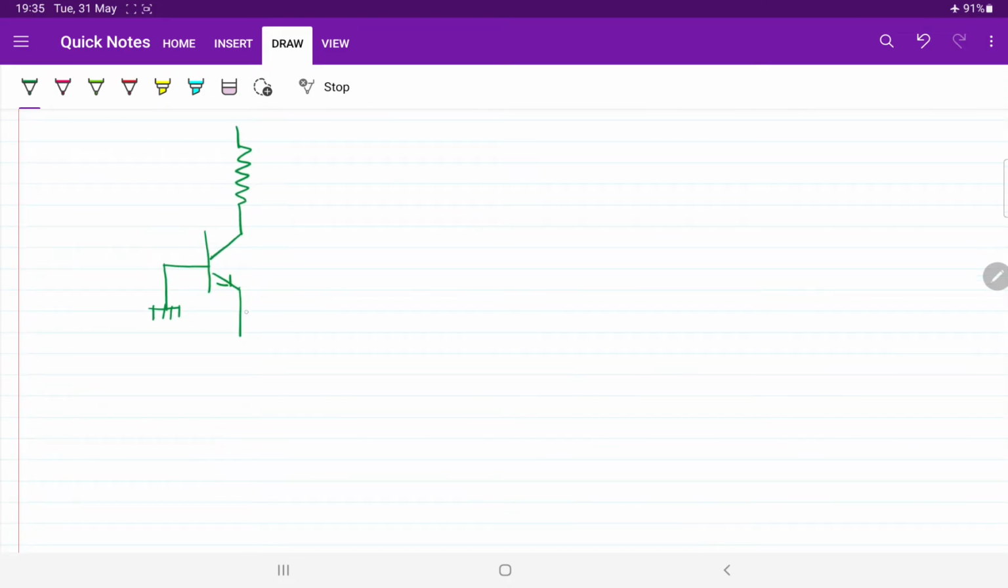And one more thing, here I told you we are considering one more diode. Why am I calling it a diode? Because I told you whenever base and collector terminals are shorted together, that circuit simply acts as a diode. So this is the emitter current delivered by the second transistor. I am calling it IE, and the first transistor also I am calling IE. If you apply KCL at this node, then this current will become 2 times the emitter current IE.